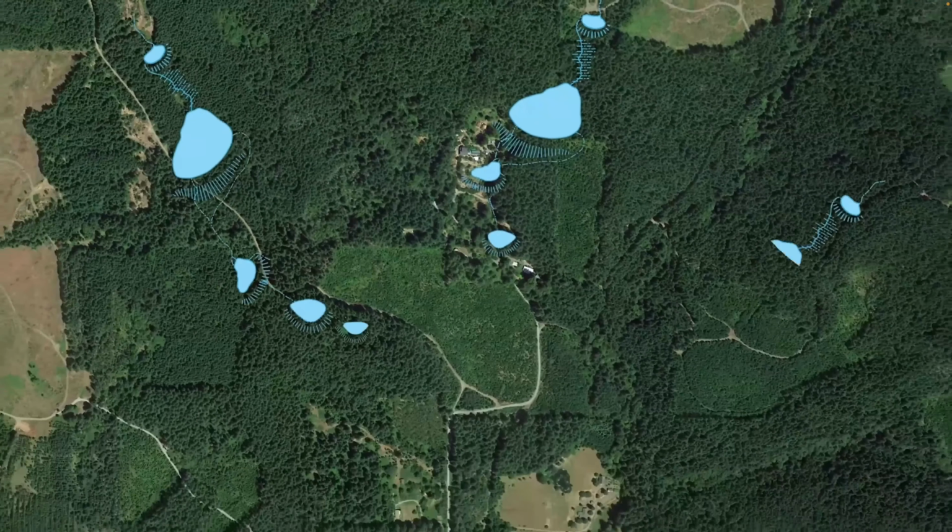A keyed dam is built with an internal key that goes up and above the ultimate height of the water. The topsoil and the less clayey material creates a skin on the top and the sidewalls. Now the dam itself also has some very critical components. The best type of dam one can build is a dam that has a central clay key.